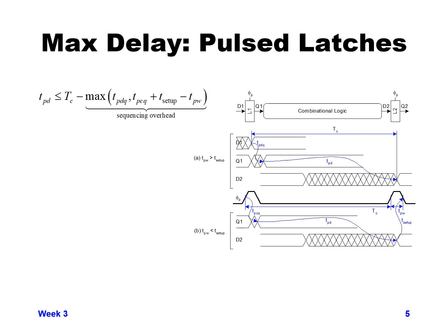So you can see pulse latch designs can also get a little bit complex. Maybe in some ways they're a little bit more complex than flop design or two-phase latch design, and in other ways they're a little bit less complex than two-phase latch, but still probably more complex than flop design. And in general, the flop-to-flop type design is kind of the easiest to navigate as far as timing goes.